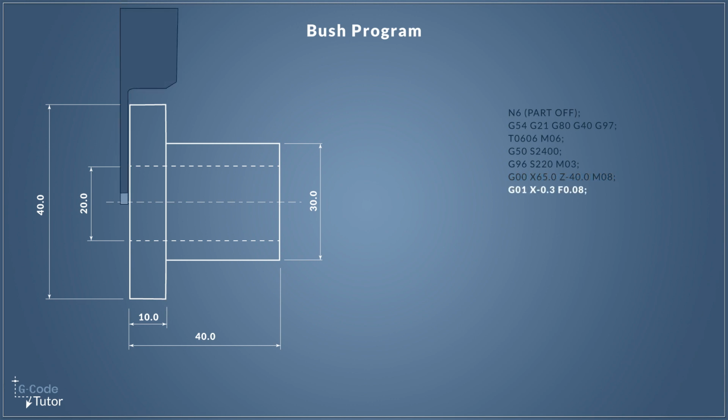In this example, I'm just using point-to-point parting off. We can use a grooving cycle for this operation also. A grooving cycle would remove a bit of material and then wrap it away. It works a little bit like a drilling cycle in that respect. But depending on the material, we don't generally need to use a grooving cycle to part off. The option is there if we have a material that keeps melting and binding on the tip, for example, or an extra hard material that might need a little help to stop the tool from breaking as we're parting off.